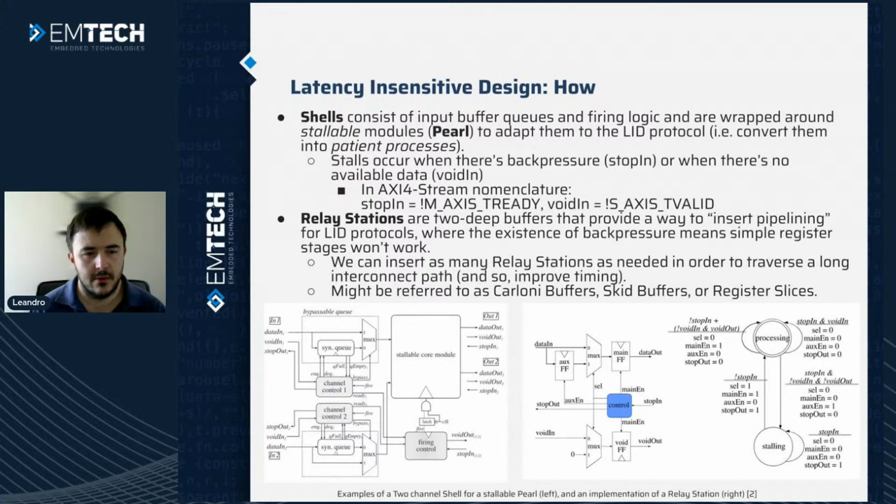Carloni and others that have investigated this propose two modules which are a core of this methodology. One is a shell, which is a wrapper for your core module, and this will adapt your core process into the latency insensitive design protocol.